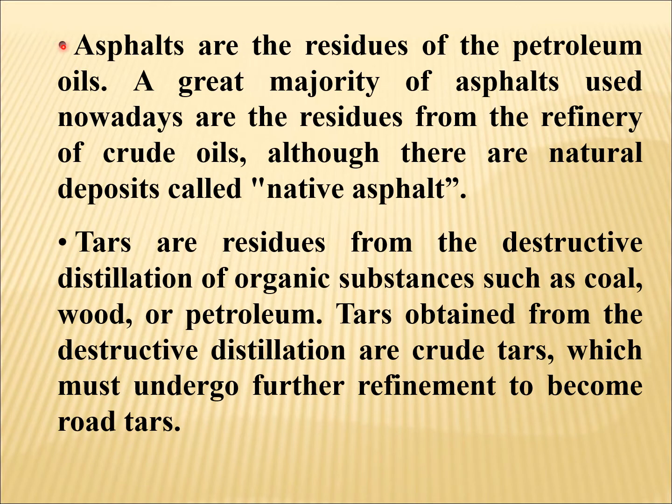As far as the asphalts are concerned, asphalts are the residues of the petroleum oils. A great majority of asphalts used nowadays are the residues from the refinery of crude oils, although there are natural deposits called native asphalt. Now look at the tars. Tars are the residues from the destructive distillation of organic substances such as coal, wood, or petroleum. Tars obtained from the destructive distillation are crude tars, which must undergo further refinement to become refined tars.